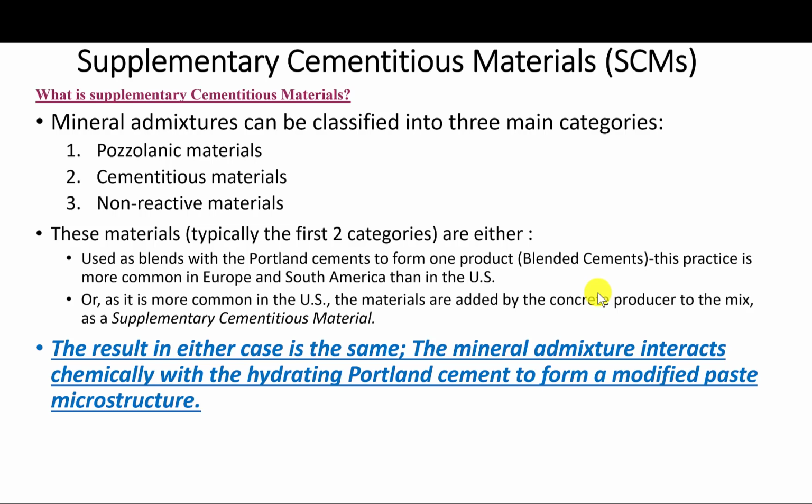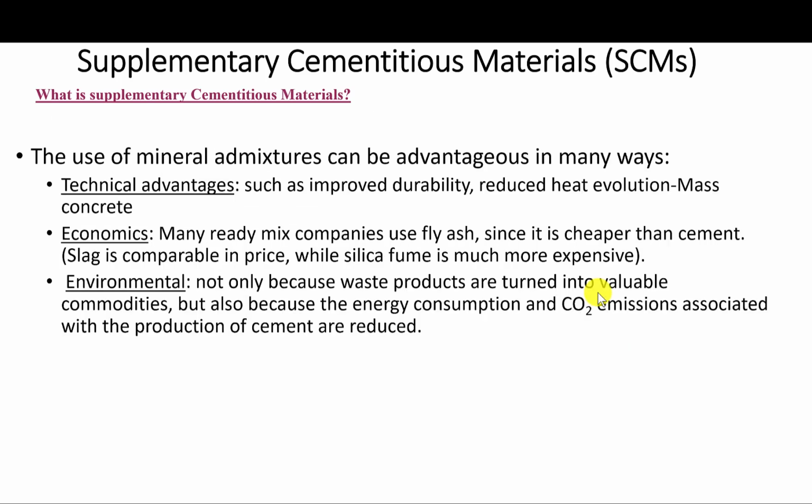The mineral admixture basically interacts chemically with the hydrating Portland cement to form a modified paste microstructure. That's how it works. The use of mineral admixtures can be advantageous in several ways. We have technical advantages, such as improved durability, as will be discussed later at length.